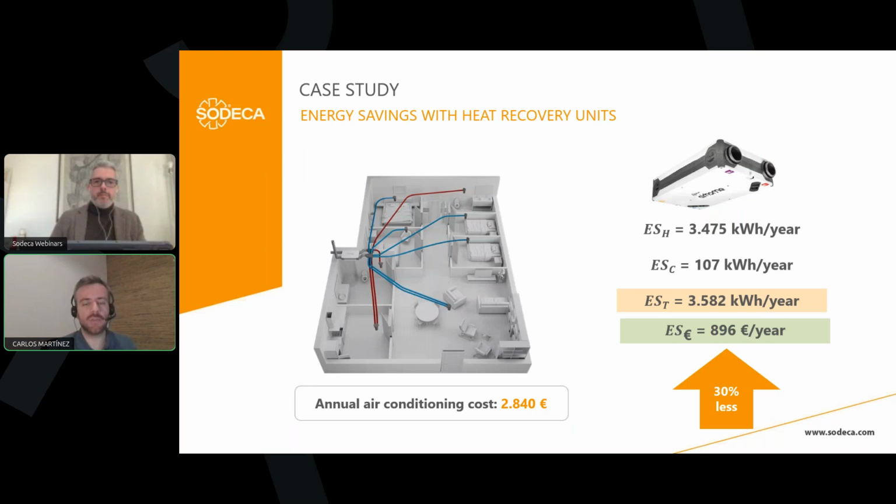So at the end of the day, you need to bear in mind that using heat recovery units is mandatory in passive house certification. But even if we are not projecting a passive house, we need to bear in mind that the return on the investment of this equipment, far from being a cost, is an opportunity, because we obtain the return in more or less 3 to 5 years. This is a function of the type of climate we have and the energy consumption we already have.